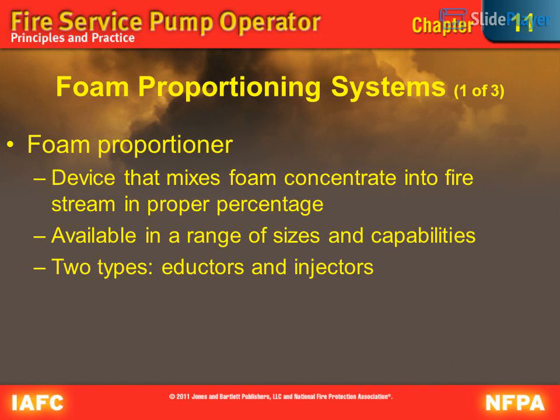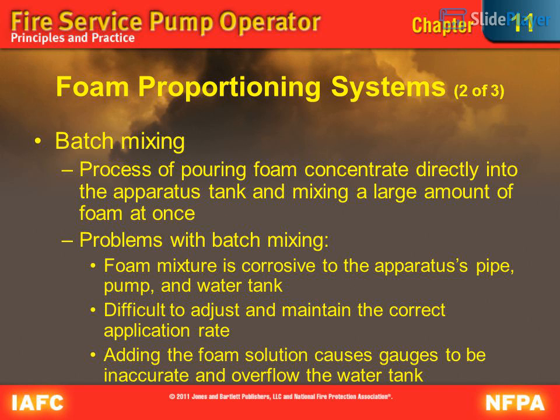Foam proportioning systems, 1 of 3. Foam proportioner. Device that mixes foam concentrate into fire stream in proper percentage. Available in a range of sizes and capabilities. 2 types, eductors and injectors. Foam proportioning systems, 2 of 3.